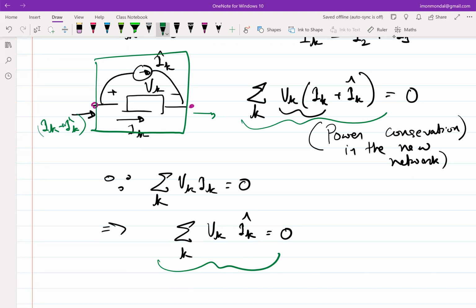Do you know the proof of reciprocity? True, but in this context, when I say in terms of circuits, what is reciprocity? If you have, let's say, a 2-port network or an 8-port network, you apply voltage at one source, observe the current in the other terminal, and you reverse, the ratio remains the same essentially, right? That's what reciprocity is. The proof of reciprocity in these conditions starts with Tellegen's. Without Tellegen's, there is no reciprocity.